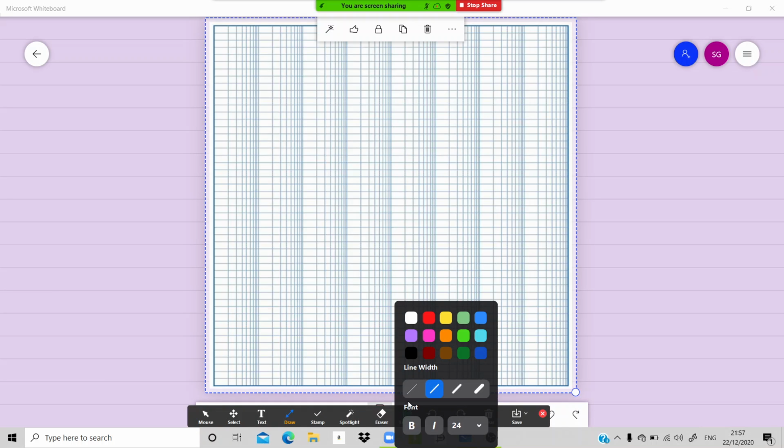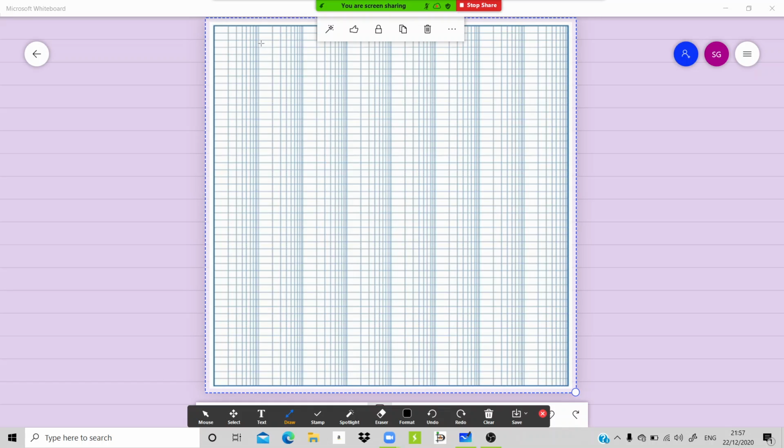So now we have to decide. Once, one of the students from Div 1 asked how you are deciding the frequency range. So now it's very much clear. We know that the first break or cutoff frequency is 1. We want to show the initial condition also. Now it depends upon you how much you can show on your paper. Those many frequencies you can take, but the critical points definitely should be included. And the phase range is minus 90 to minus 270. So I think we'll get it fitted over here.